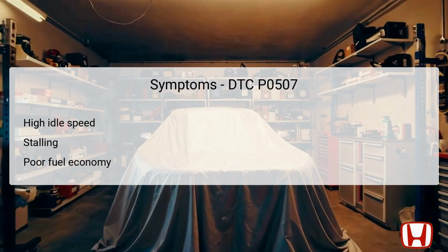When DTC P0507 is triggered, various symptoms can arise in the vehicle's performance. The most noticeable symptom is an excessively high idle speed, which can lead to a rough engine performance and vibrations while stationary. This condition can contribute to stalling, particularly when the vehicle is coming to a stop or during low-speed maneuvers. Furthermore, drivers may notice poor fuel economy due to the engine continuously running at an elevated RPM, leading to excessive fuel consumption.